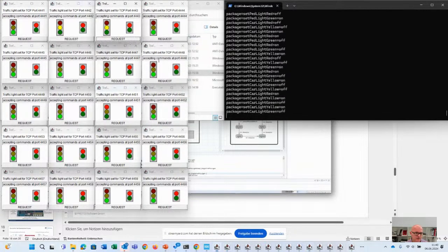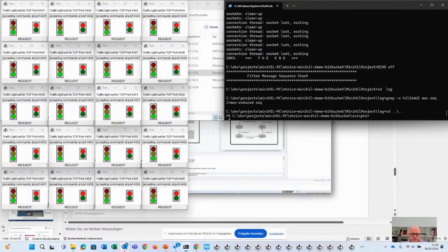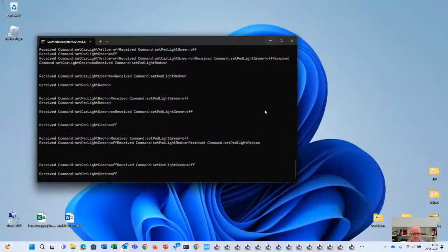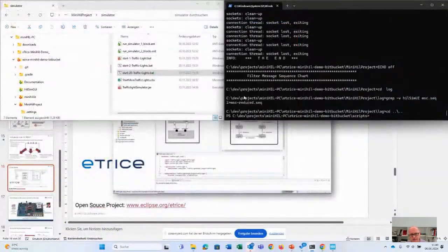So as you can see, and that's always robust, it always works, because 90%, 95% of whatever I do is generated. So that's the scalability of the system. And now I'm going to show the last step. Last step is I want to make a software in the loop test, because I'm not always there to click whenever I change my application. I want to automate this test.